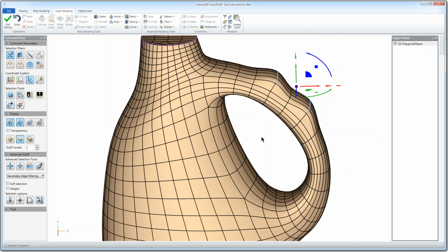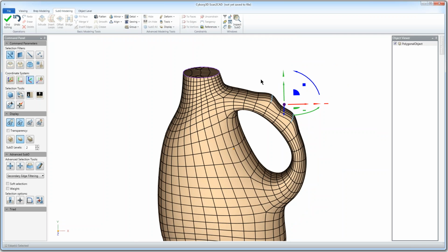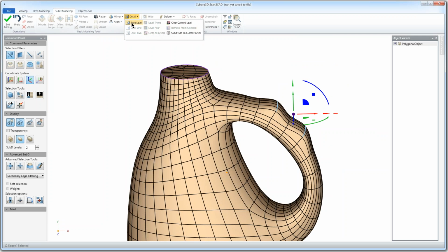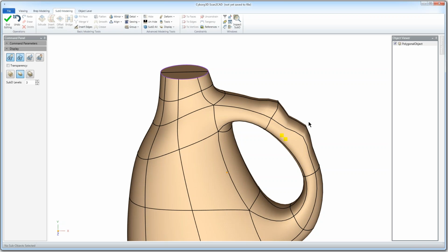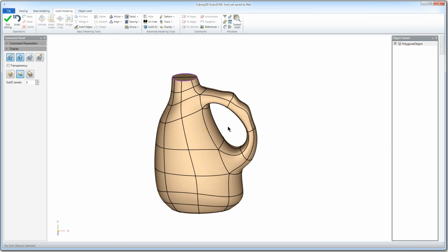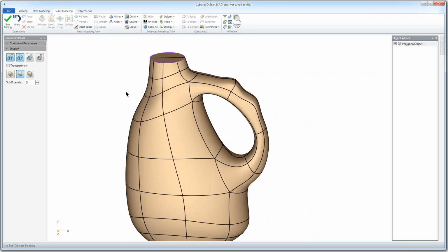And make a little bit of a shape to put your thumb on there, so you can easily tip it upside down and dump it out. And now when we exit the level of detail, we go back to the base level, you can still see those modifications there. You might actually want to go to a little bit finer level of subdivision so you can see them better. Because what happens is that detail is embedded in a subdivision level. So if we were at 2 subdivisions, you go back to 2 subdivisions, you can actually see the exact level that we were working on.